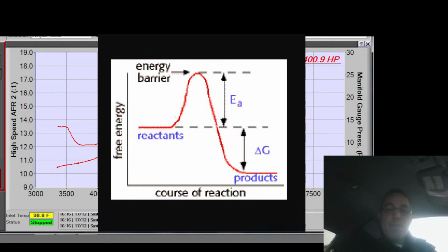So, how does that all affect our heat range? Well, we need it to be hot enough to clean, but cold enough that we're not causing pre-ignition events or retaining a bunch of heat in the cylinder, and cold enough that we don't melt the electrodes. So I guess three things: don't melt the electrode on the end of the plug. So that's how it plays in. That was a long explanation, wasn't it?